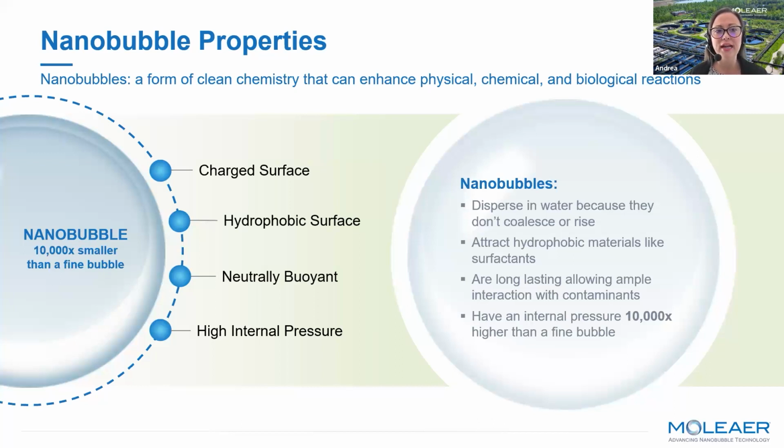Nanobubbles disperse in water, and they don't coalesce, and they don't rise due to buoyancy. They attract other hydrophobic materials like surfactants and fats, oils, and grease to their surface. They're also long-lasting, stabilized by the contaminants in the water due to that obstruction, such as we saw on the previous slide related to oxygen transfer in surfactants. Because they're long-lasting, they're able to interact with many contaminants in the wastewater. And they also have an extremely high internal pressure, 10,000 times higher than a fine bubble.